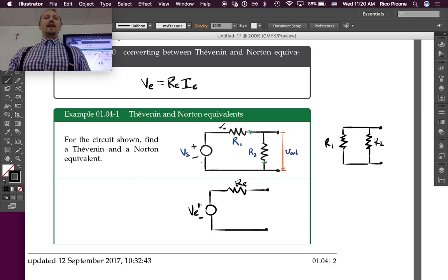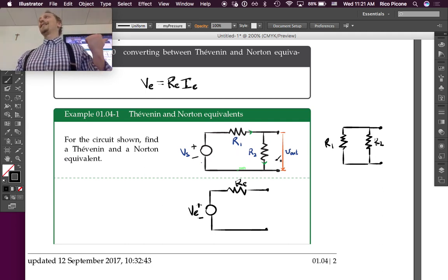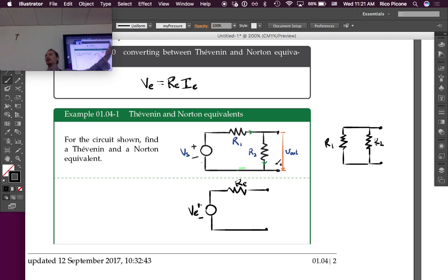It's because if this is replaced by a wire, all of this is one node. And it's not until we redraw it that it becomes obvious that these two resistors are then in parallel. Before we shorted out the source, these two resistors were in series. Now they're in parallel. I know, it's like, whoa, mind blown moment right now.